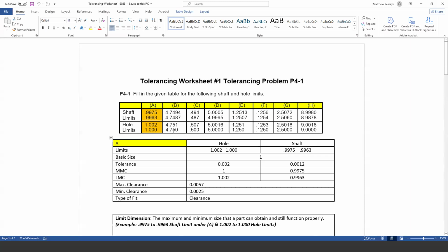In this case, it's probably 3/4 that is the basic or nominal size. If it was C that we were working, it's a 1/2 inch basic or nominal size. This is a 5 inch basic or nominal size. This is a 1 1/4 basic. So I'm using the bottom row as my basic or nominal size here, which maybe wouldn't be widely understood, but maybe you could take a guess at that. If you looked at all four of these dimensions together, you'd ask which one they are probably all based around. That's a 1 inch fit.